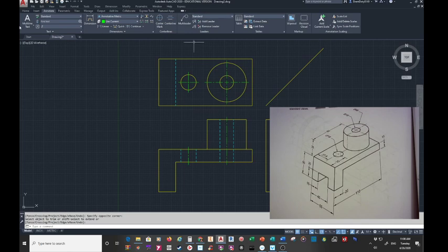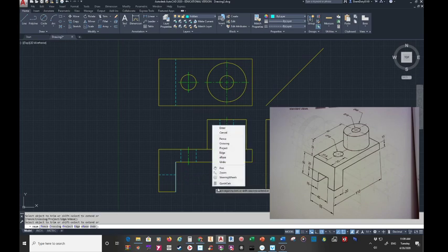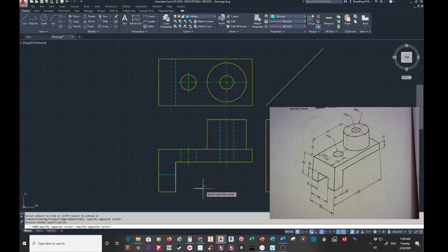I'm going to go ahead and go back home. I'm going to change this to hidden, and I'm going to draw me a line, and I'm going to project from here over to here, like so, and I'm going to trim it up. There's more than one way to get to Rome, like Mr. Anderson says. It's not wrong, it's just different. So there's multiple ways to do this. But like I said, I'm working on each view, getting it so far, and then I go work on another view until I need to find something else.